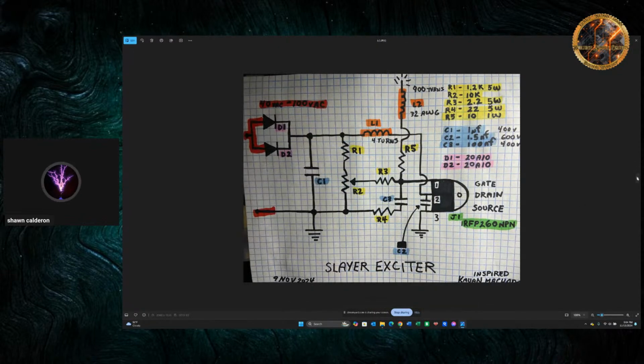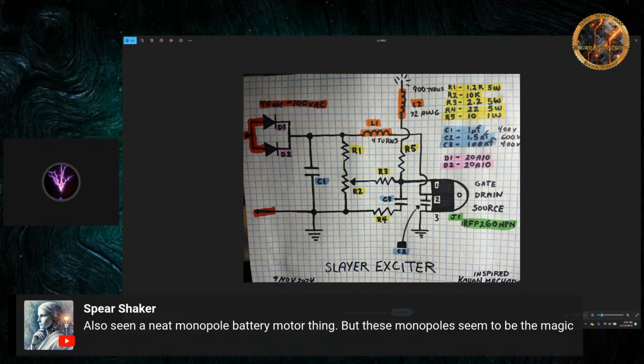Now, this was my endeavor to improve the Slayer exciter circuit. As you know, Nathan has these very amazing Slayer circuits that he beats up all day and they keep on running. With this overcomplicated Slayer exciter circuit, what I was trying to do is just protect the MOSFET. These extra components, when you normally only need 3 components, are to try to protect the MOSFET, yet keep it a Slayer. The reason why I bring this up here is because it's one of my prototypes.